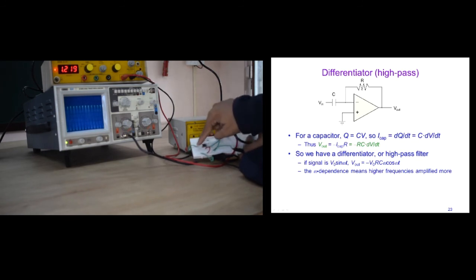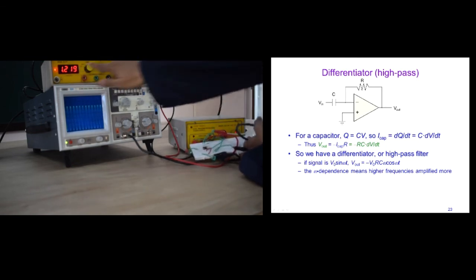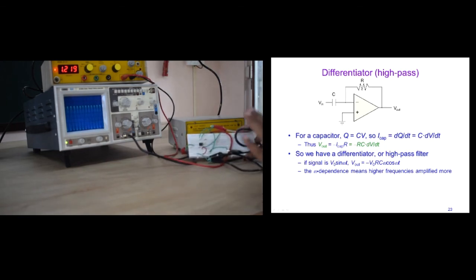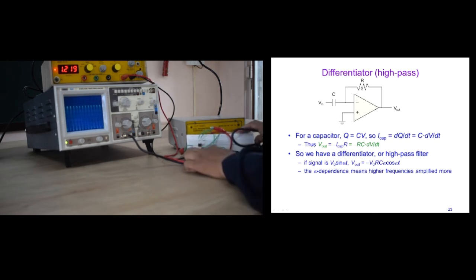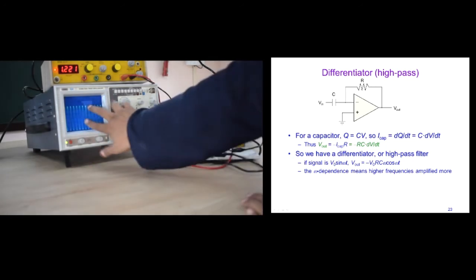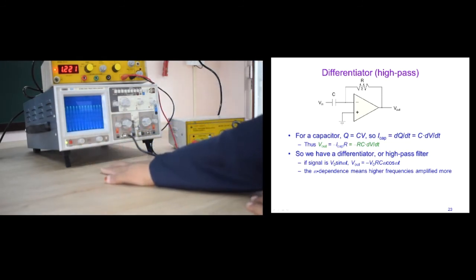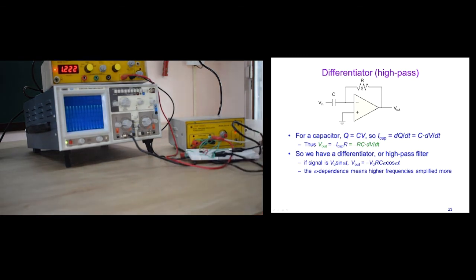The capacitor has been placed at the input and given to the signal generator, and you can change the frequency. We can change the input frequency and the output. We are keeping the input at 1.2 kilohertz, and this is given to the capacitor, and the capacitor is connected between the input and pin number 2, and we have connected the feedback. Here you will observe the output on the CRO, and you have to measure in a similar way the consecutive crests or troughs for observing the output.